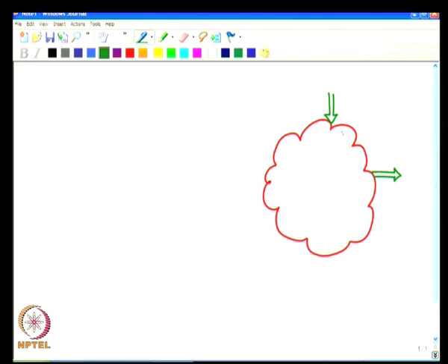We have the plant, which is the DC-DC converter. It could be any DC-DC converter, and this converter is having a power input, which is Vg. It is having a power output where we have V naught. It has one control input. The control input is D, duty ratio. It has an output to be controlled Y, that we call, which is sensed and taken from the power output V naught.